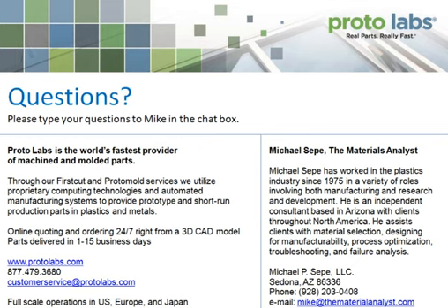So the more polyethylene you put into the material, the more likely you are to shift the flame rating. And of course, a lot depends upon the letdown ratio of the concentrate, something we didn't talk about. Now, letdown ratios are usually 3, 4, 5 pounds per 100, but I know people who are using 10 pounds per 100 in order to get better incorporation of their color into the base resin. So that means they're using more carrier resin than they typically would. So if that carrier resin is not compatible, and if it's a material that is a little more prone to burning than the resin they're putting it into, it can shift.